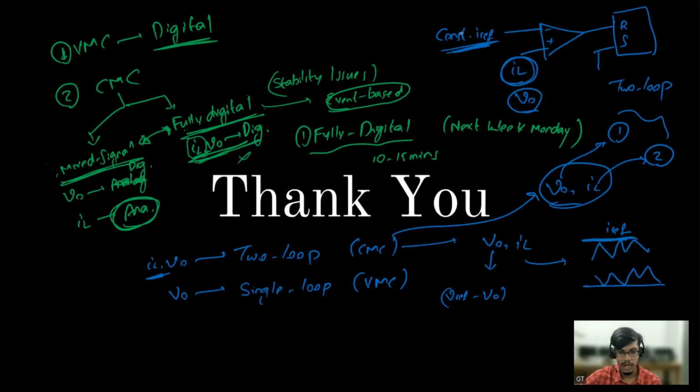So this outer loop I am opening. I am only giving constant I reference. So there is no V0 loop. In this case, V0 is not regulated. If you want V0 to be regulated, you have to use two loops.